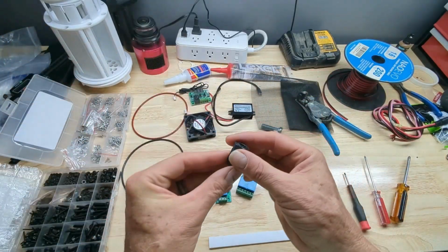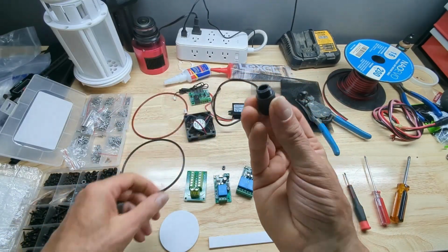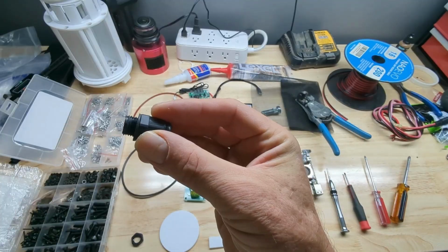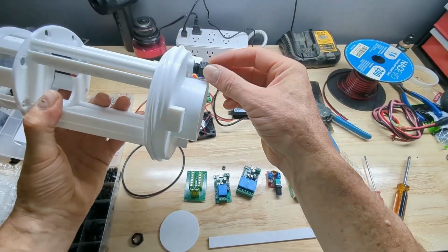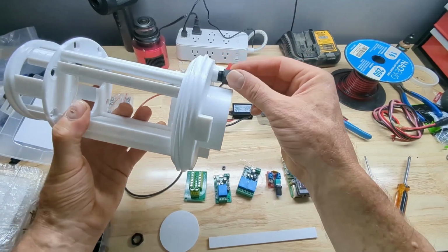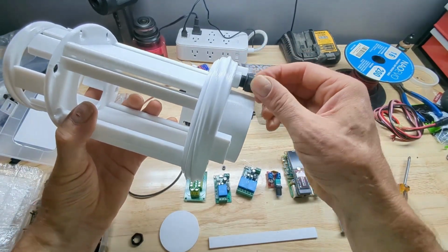So this is the wire gland I'm talking about. We'll take this nut off the end of it, and you'll see it's threaded. Let's see those threads. And what that does is it just threads right into this hole. It's hard to do with the camera right in my face, but yeah, it'll thread right into the hole. Just make sure you don't cross the threads.